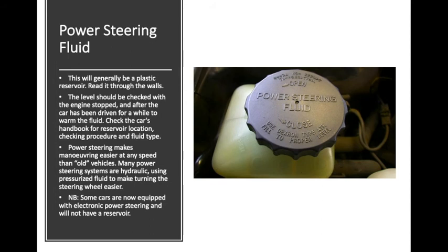Power steering fluid. This will generally be a plastic reservoir, and you can read the measurement through the walls. The level should be checked with the engine stopped and after the car has been driven for a while to warm the fluid. Check the car's handbook for reservoir location, checking procedure and fluid type.